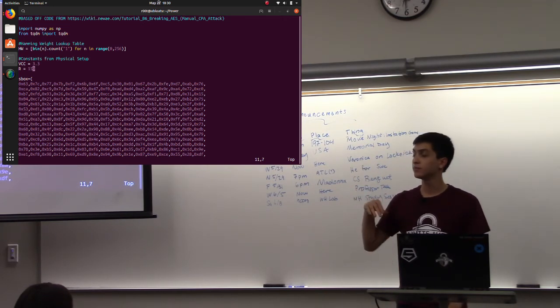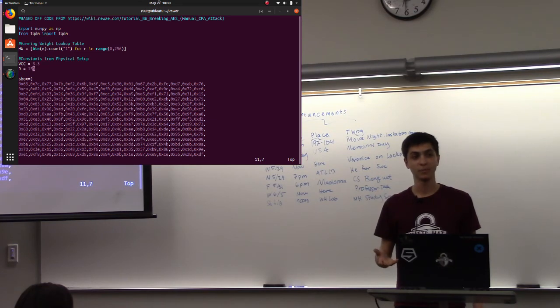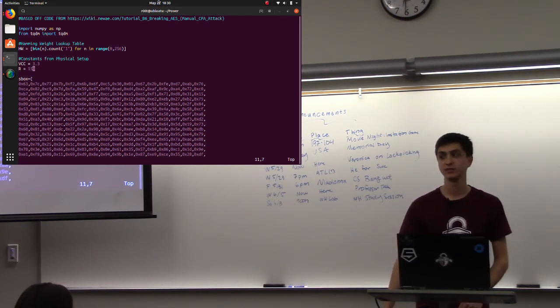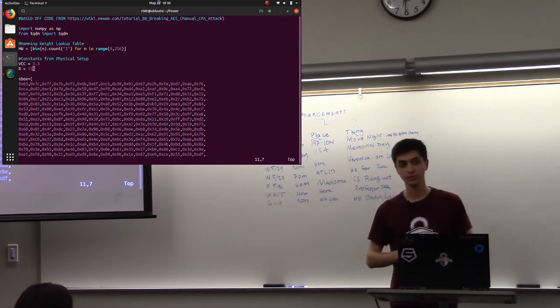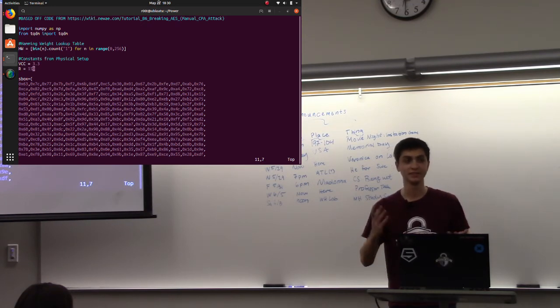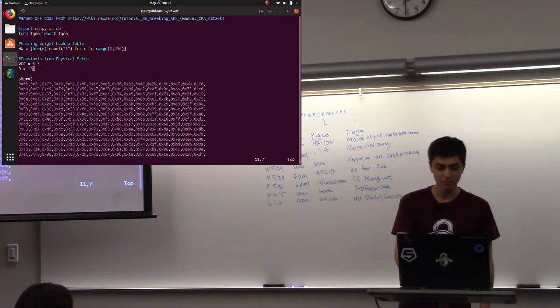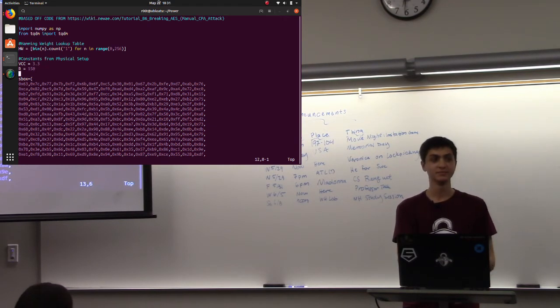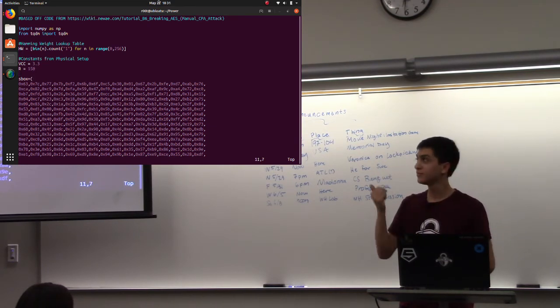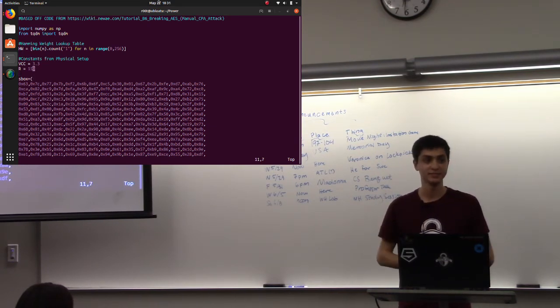We're going to end up calculating the power, and we'll see the equation we used: the power is proportional to the voltage that we measured. So we can actually just not do that calculation and use the voltages, because you're just trying to maximize the correlation between the two things and not the actual values. So it actually doesn't really matter. And the 150 is the value you'd read off the bands on the resistor.